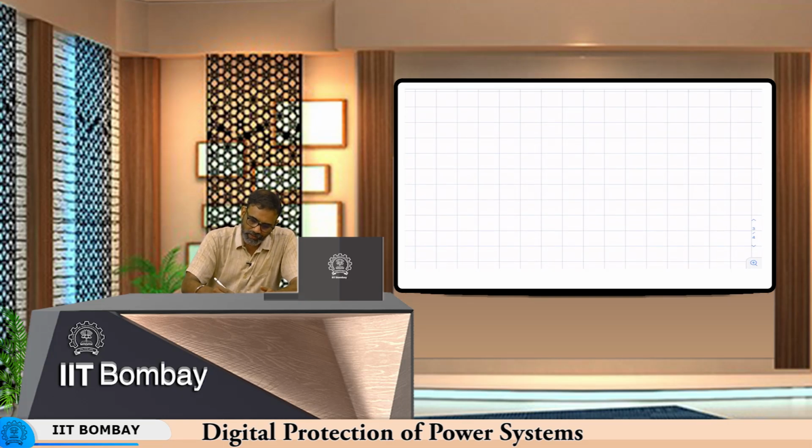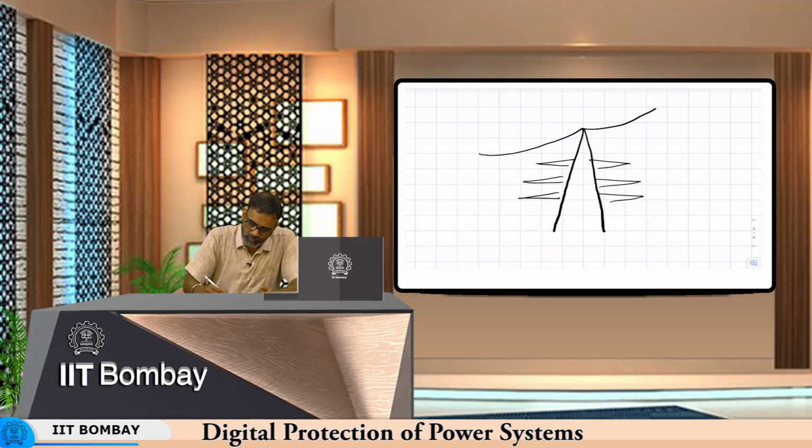You are aware of how a transmission tower looks. We will just take a single tower for the discussion here. There is a shield wire on the top of the transmission wire. Some transmission towers will have two shield wires. Then there are cross arms. I am drawing a double circuit tower here. You could have a single circuit tower also. This is a steel lattice structure which is grounded. Then there are insulators, and then there are conductors, this round part is the conductor.